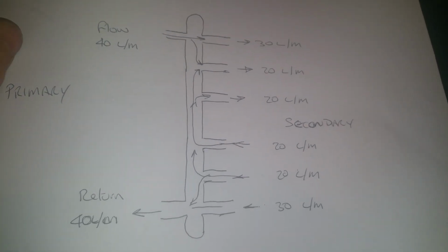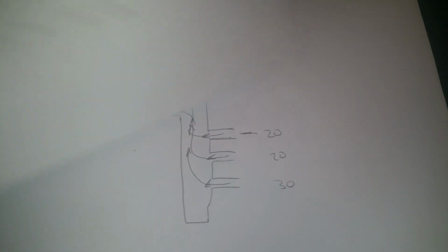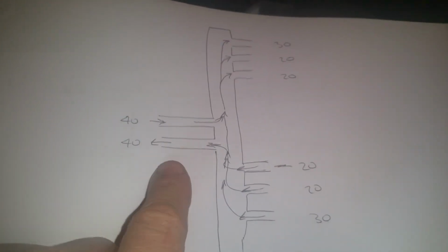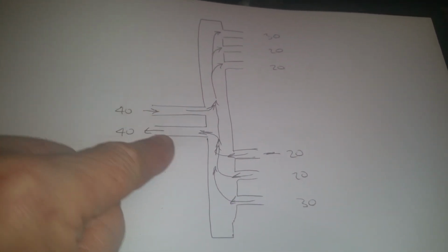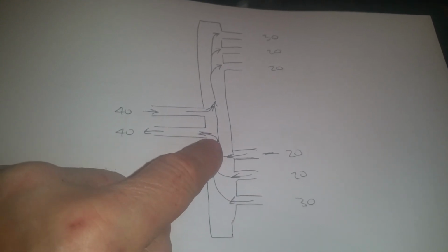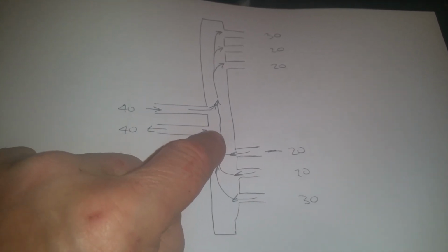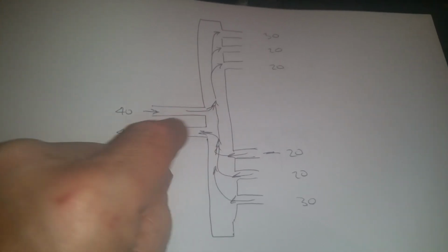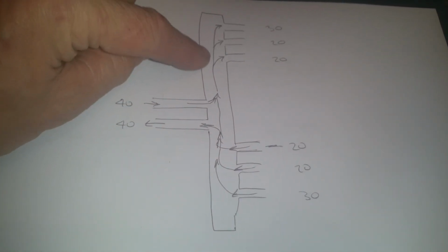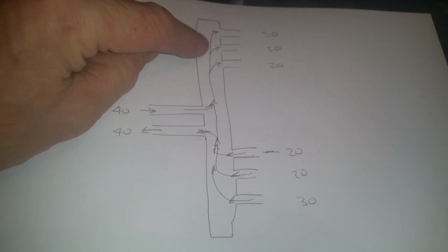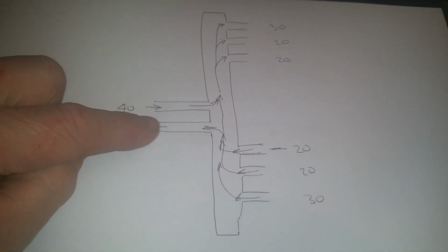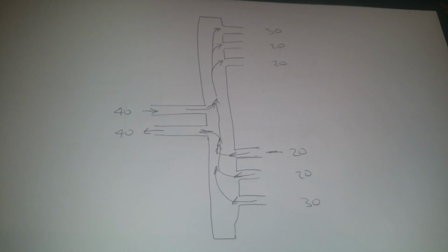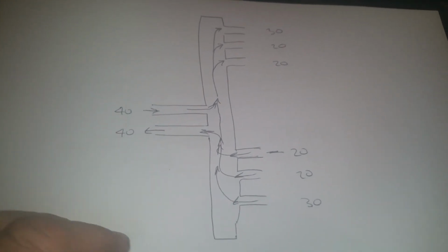If you need to lay it out on that kind of header, if you were to actually put the two connections for the boiler in the centre here, then any surplus flow from the returns has to mix with our flow water, and so we get an equally mixed distribution temperature and the correct flow rate off to these three circuits. So that's a simple modification that will give you the correct performance.